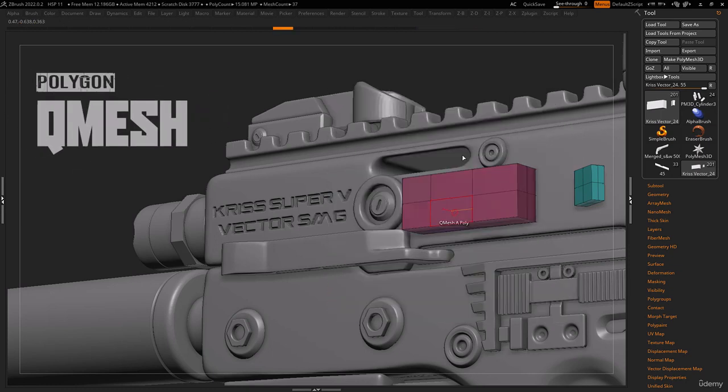With the Q Mesh action selected, with one click you have the ability to extrude polys in combination with snapping and merging to adjacent polys. Q Mesh will connect to polys varying in size similar to the bridge action. In addition to extruding, holding the Shift key will pull the poly instead, and holding the Control key will duplicate and offset the poly. You can definitely get a lot done with Q Mesh.